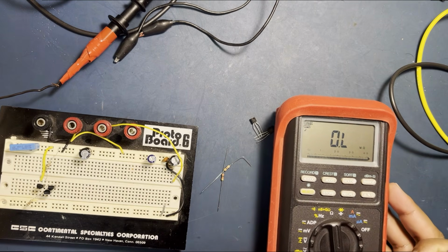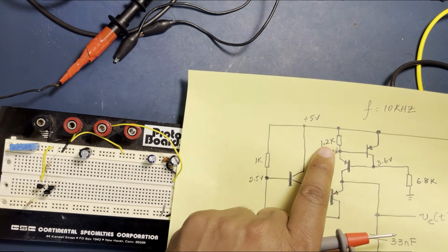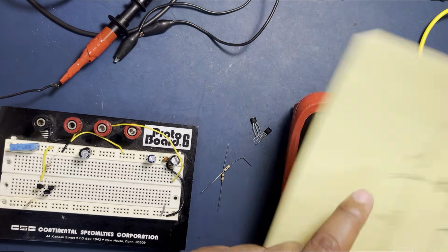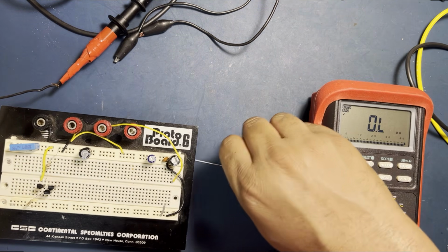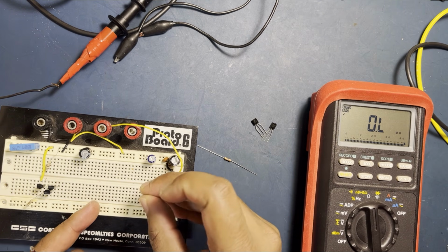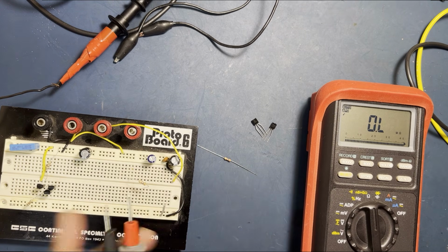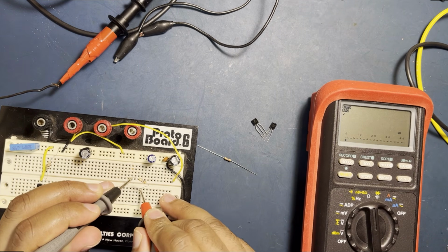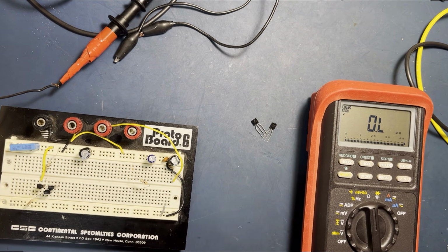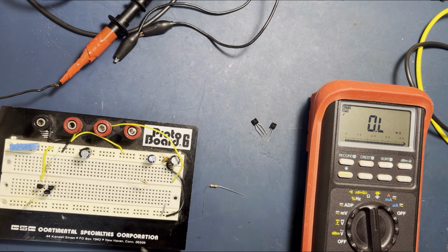So I just want to show you something quick as well. I don't have the 1.2K that we designed for this side. So what I decided is to use 3K and 2K in parallel. That's the closest value I have that's going to give me 1.2K. So here is a 3K resistor, right? I'm just going to put it here in parallel, so you can take a look at this. There you go. It's 2.953K. And then if I put the 2K resistor in parallel with it, I'm just going to quickly measure it before we put it in.